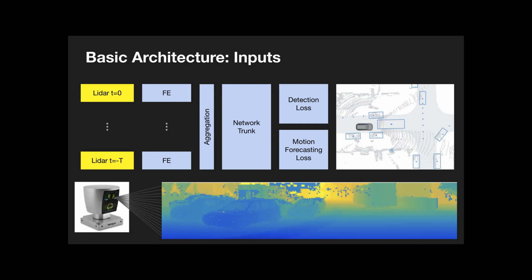Since this sensor spins multiple times per second, it is important to capture at least 2 full spins to have a chance to see each object twice at different times. You could alternatively use two different lidars scanning at different times to get the same effect. This is required to get velocity. In practice, most algorithms will take more than 2 spins for robustness, and also use multiple lidars, for capturing higher motion states, such as for instance acceleration.